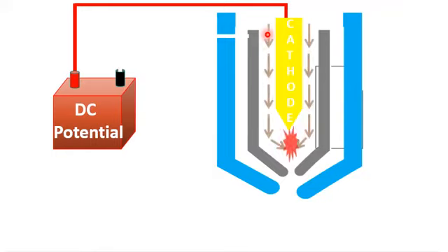The arc, which has a very high potential at the cathode, will result in the ionization of the incorporated gas. When the external gas interacts with the arc, which is operating at a very high temperature of thousands of degrees centigrade, it results in the formation of plasma inside the plasma arc igniting system.